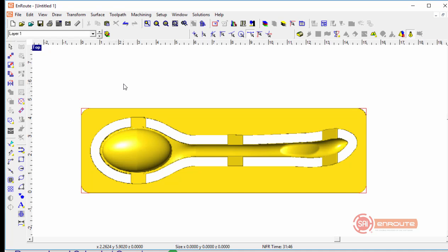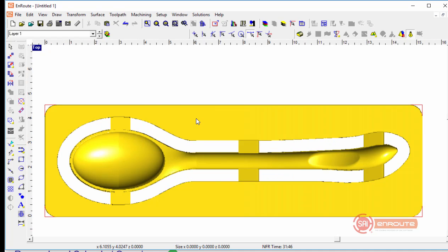Well, actually, maybe what I'll do is create side 2 first. And one of the things about flipping this part is we need to make sure that there's some way that we're able to flip the part and make sure on side 2 that it's exactly where it lines up with side 1. We can do that by cutting a couple of, say, 1/4-inch dowel holes a certain distance from the edge of the part, and just make sure that when we flip it, that we go right back into that same dowel hole position. That's one easy way to do it. Or you could cut the shape out or have a fixture. There's lots of ways that can be done, but that's an important part of the process.